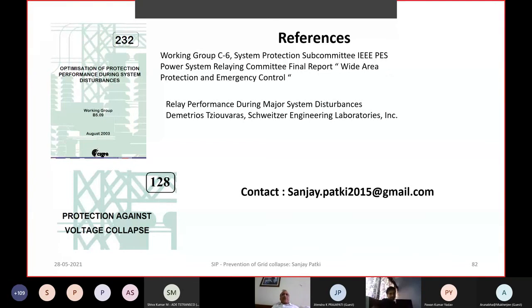So when you charge a transformer which already has a fault, the inrush current will not prevent the relay from operating. The differential relay will operate. Correct. And a similar function to the high set is there even in modern numerical relays, where the fundamental component is also checked concurrently along with the second harmonic measurement.